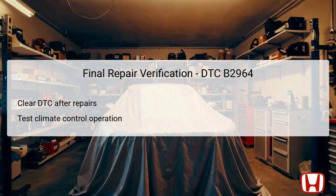repairs have been successful. Start by clearing the diagnostic trouble code from the vehicle's memory, which can be done utilizing a diagnostic scanner. Following this step, conduct a thorough test of the climate control system to ensure that it responds appropriately to inputs from the climate control switch. Observe the system for any anomalies or failures during this testing phase that could suggest an incomplete fix. A successful verification process not only confirms the effectiveness of the repairs, but also ensures that the vehicle is ready for safe and comfortable operation.